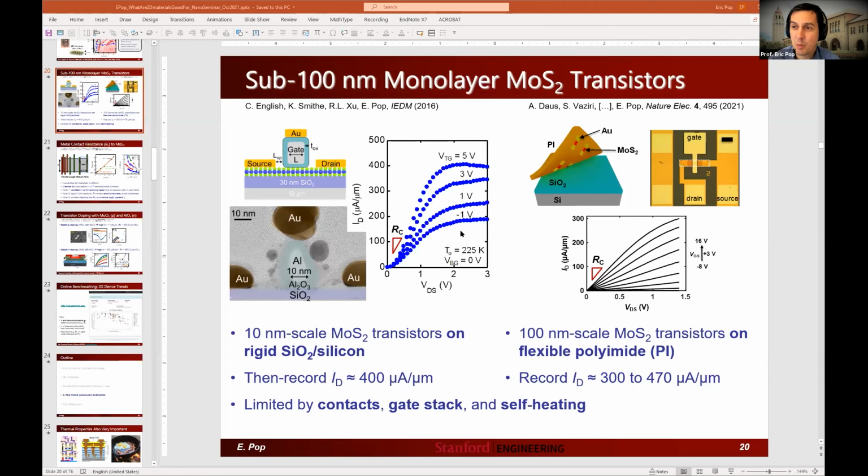Boron nitride, the K is similar to SiO2. And so it's just not good for low voltage switching in these transistors. Even though obviously by itself, it's a wonderful heat spreader, if you can get it. But I just think fundamentally boron nitride is the wrong dielectric material, at least for low voltage switching in transistors. It could be used as an interfacial layer, but that would need to be followed up with a high K dielectric. Now, if you're aware of 2D dielectrics that have high K and they play well with 2D semiconductors, then I'd like to know about that, because that could be very, very important.